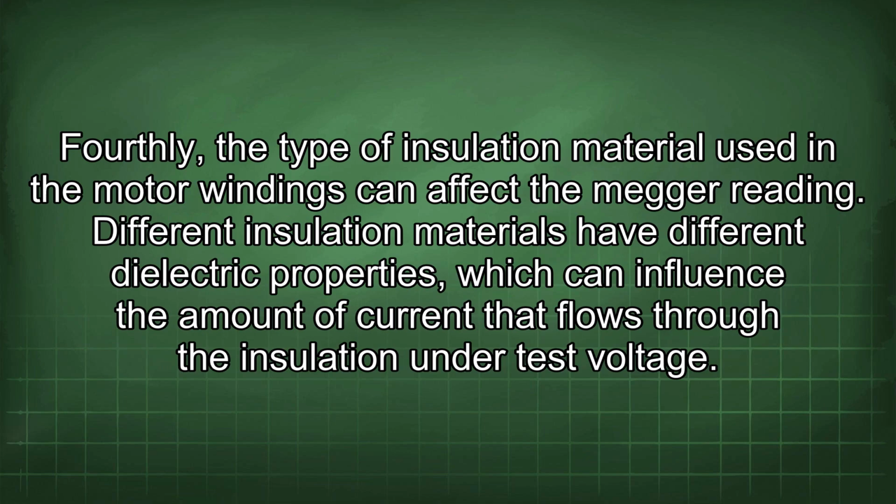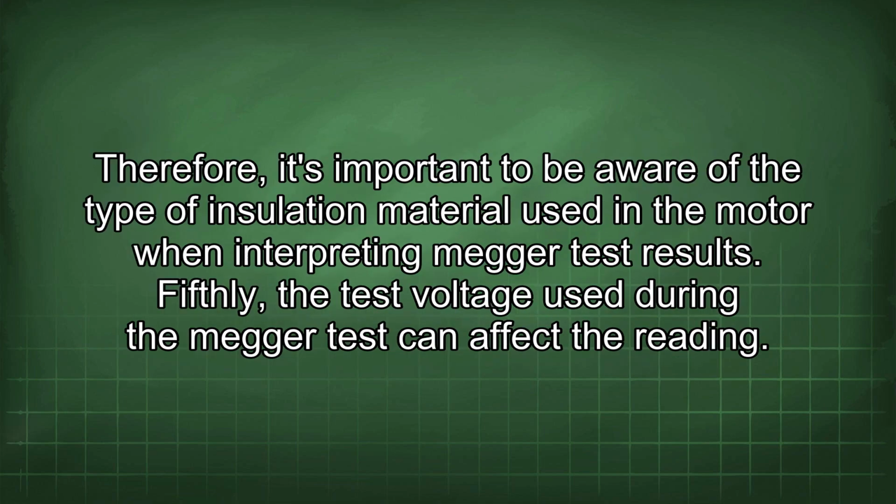Fourthly, the type of insulation material used in the motor windings can affect the Megger reading. Different insulation materials have different dielectric properties, which can influence the amount of current that flows through the insulation under test voltage. Therefore, it's important to be aware of the type of insulation material used in the motor when interpreting